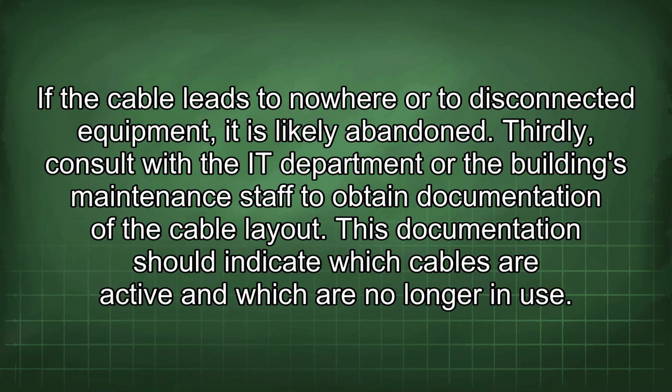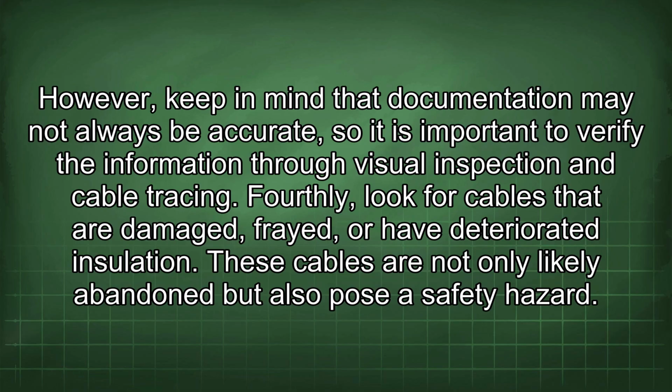This documentation should indicate which cables are active and which are no longer in use. However, keep in mind that documentation may not always be accurate, so it is important to verify the information through visual inspection and cable tracing.